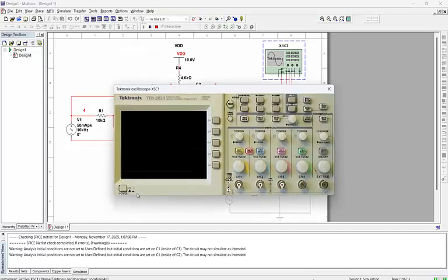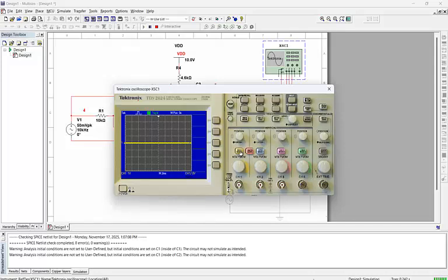Open the Tektronix oscilloscope. You have to open channel 2 and channel 3, and enlarge the volts per division for all of them in order to properly see the signal. You could also vary the position in order to check clearly the values of the signals.